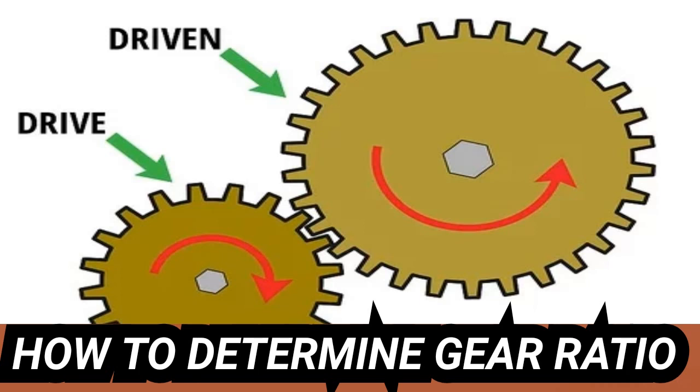Question: how do I determine the speed ratio between two gears given the RPM of each? Community answer: simply divide the two numbers the same way you would if you had the number of teeth of each gear. Question: can we mesh a gear having 200 teeth with a 15-tooth gear? What is the effect of the gear ratio? Community answer: yes. For each 1 RPM of the 200-tooth gear, the 15-tooth gear does 13.33 RPM.